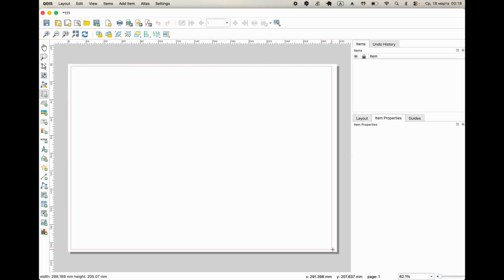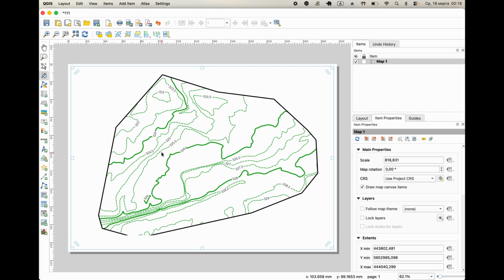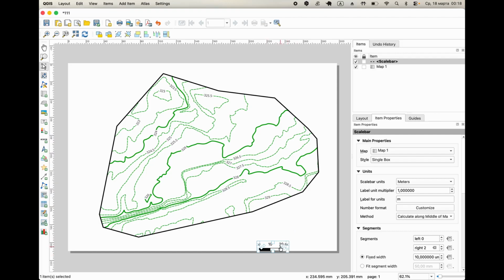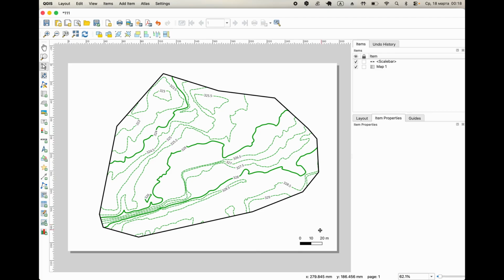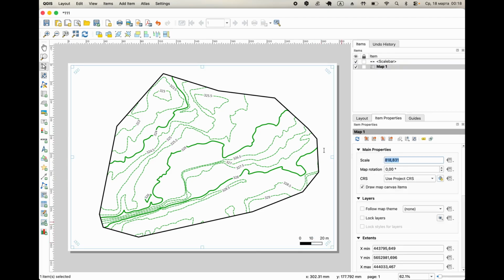So to summarize this QGIS stage, we start with the elevation raster, generate contour lines, clip them to the relevant area, remove very short contour segments, create a clear visual hierarchy through styling, and then prepare the final layout for export. So this last part of the workflow is where processed terrain data becomes a readable map.